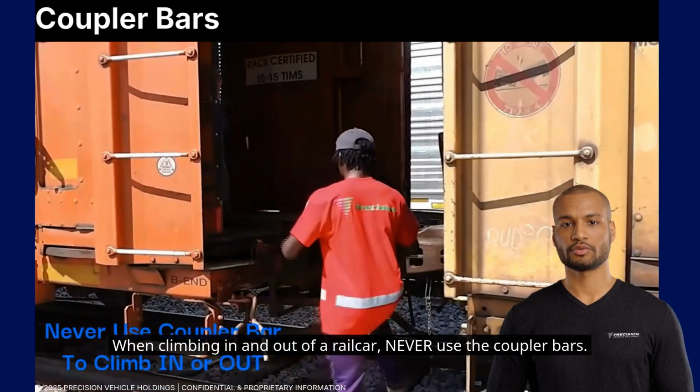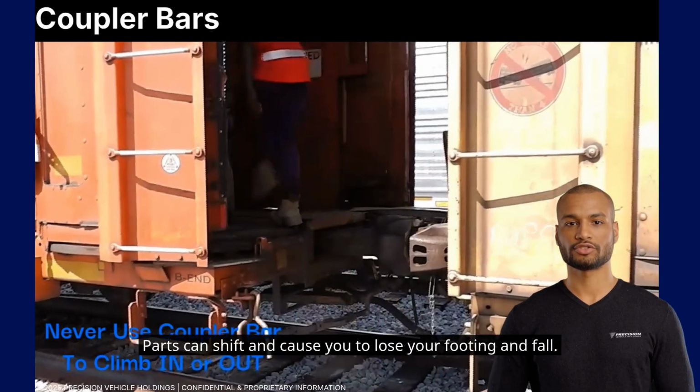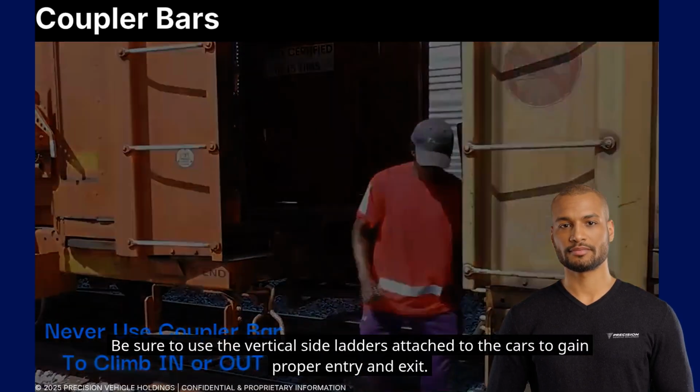When climbing in and out of a railcar, never use the coupler bars. Parts can shift and cause you to lose your footing and fall. Be sure to use the vertical side ladders attached to the cars to gain proper entry and exit.